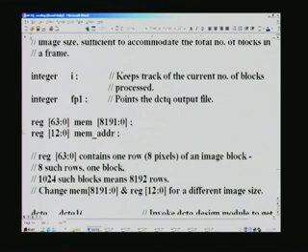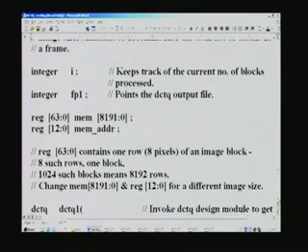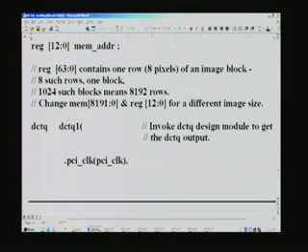This we have seen before in the external memory design earlier. Here we have 8192 locations in total, each being 64 bits, and this much memory is required to hold 1024 blocks of the 256 by 256 image, which is related in terms of number of bits. For the address you need 13 bits, because it is nothing but 8K, and that is what it says here. We now invoke the DCTQ design and list all the IOs therein.